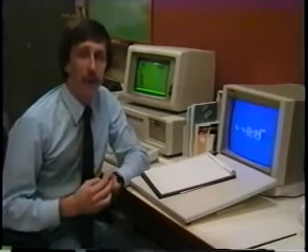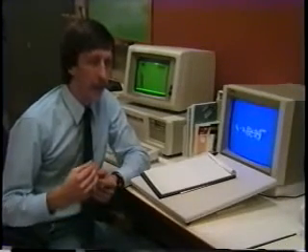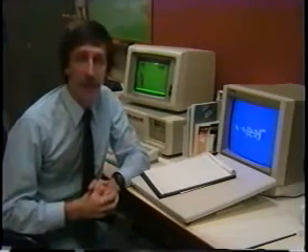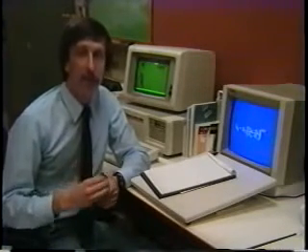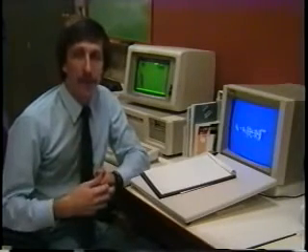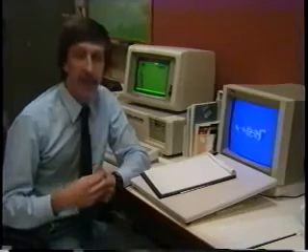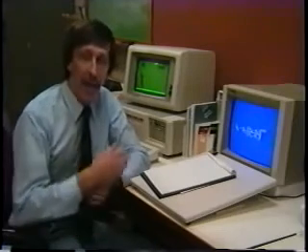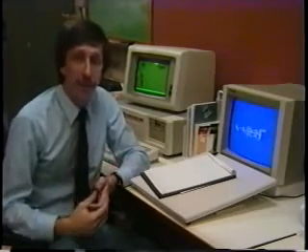If all you were going to do, though, with the results of the test is simply store them on the computer, the computer wouldn't be worth the investment. Instead, the real power of the computer is when you can take the results of the flow test, use those results to calibrate a computer model, and then use the model to do more things. You see, a computer model is very easy to calibrate if all you do is observe normal operating pressures. But if a model can be calibrated for normal operating conditions and calibrated to reproduce the results of a flow test, you could have a lot of confidence in it. It's a very credible model.